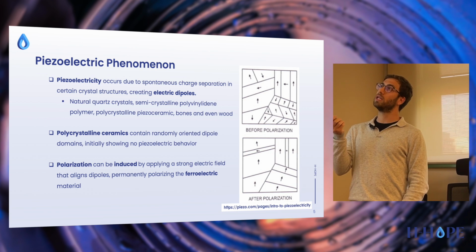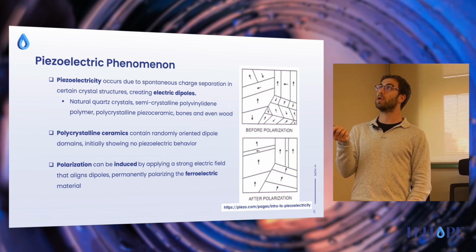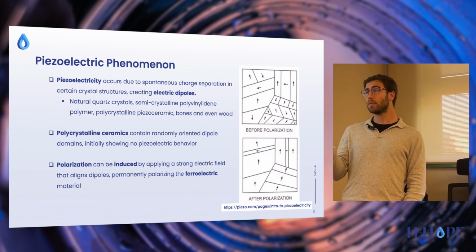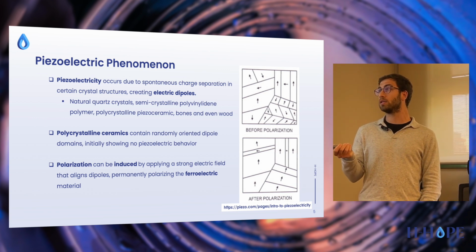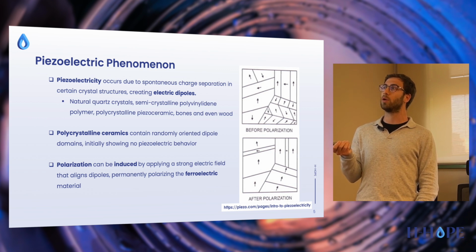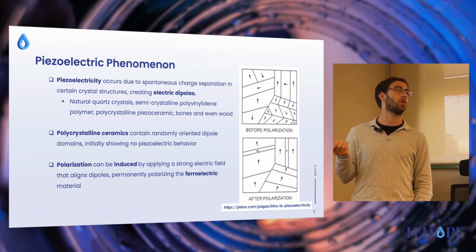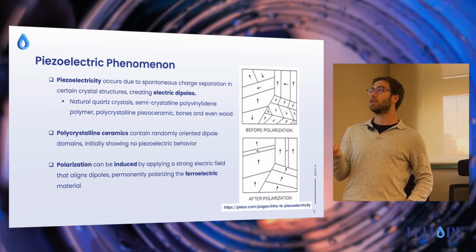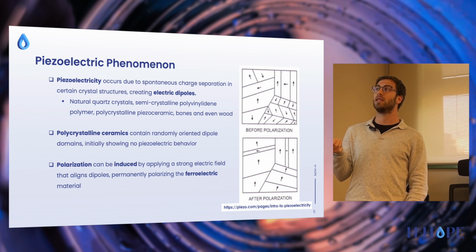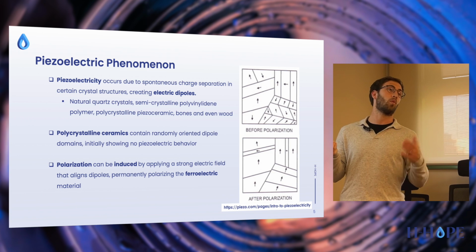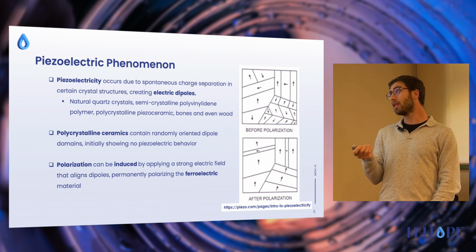There are materials like quartz, which are piezoelectric by nature. Basically, they are made of silicon and oxygen. Because of the crystal structure, if we put some pressure, the oxygen has some negative charge and silicon has some positive. If we apply pressure, the structure is modified and then there is polarity, on one side or the other, depending on whether it's under tension or compression. That helps us understand how we can obtain one polarity or the other.